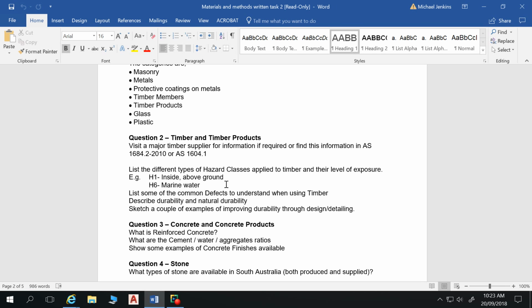Yeah, so we think about a bunch of structural things. Well, I think if I'm using timber stumps, what do I want to do with timber stumps? I was thinking of the green stuff, copper chrome arsenic. Yeah, H3. Okay. So once again, that's a treatment.